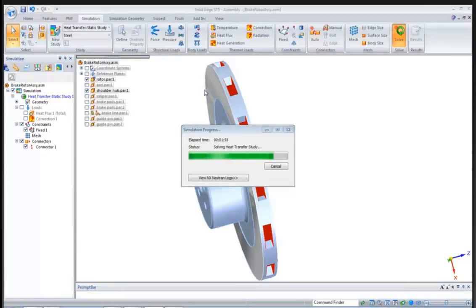So those are heating up the air molecules with diffusion. Also, those air molecules are going to start to rise because they're getting warmer and less dense. So you've also got this bulk fluid motion. So you've got two forms with convection: the bulk fluid motion, which is called advection, and the diffusion that we were talking about. So there are two forms of energy transfer with convection.